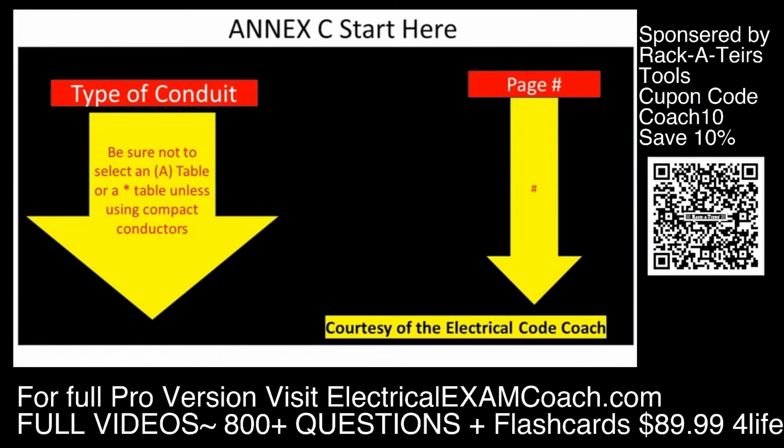But for your normal pipe fill questions, they're not compact conductors. Matter of factly, unless it says the word compact conductors, you will never assume that they're compact conductors. And you do not want to use the A versions of these tables. So when you go to the first one, it says C1 EMT. And then the second one is C1A. That's letting you know it's a compact conductor table. Now let's imagine that we did want to go to EMT.